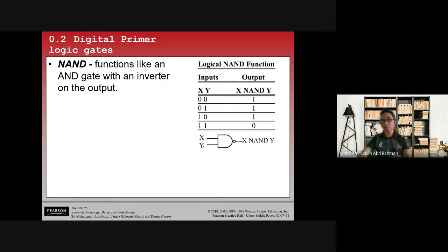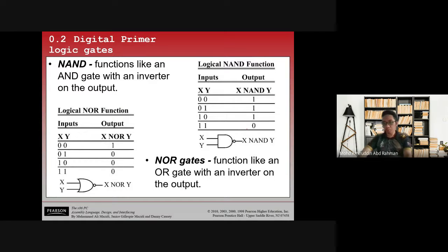Okay, and NAND. So it is the inverse of AND, the inverse of the AND. AND is about the multiplication. So for AND multiplication, normally 0 0 gives 0, 0 1 gives 0, and only 1 1 gives 1, because you multiply. But NAND will invert, alright. So NAND turns 1 into 0. NOR is the same. Like NAND, it is the inverse of the OR. Only 0 0 will become 1. All the others will become 0.